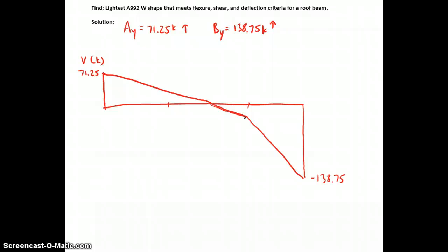and that means we're going to need the values of moment at the quarter points. So in order to get the values of moment at quarter points, we're going to first solve for the value of shear at those quarter points. So while we're here on the shear diagram, I'm going to label the quarter points of each shear segment, which you can easily get by looking at the value of loading in the loading diagram above.